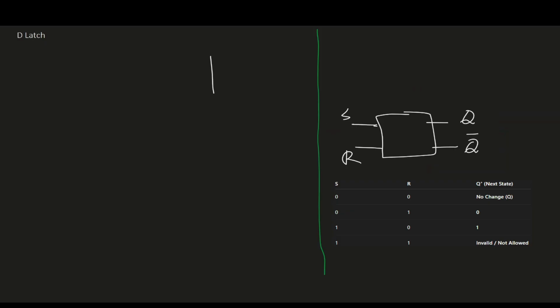So let's take this SR latch. We have the set input and the reset, and we have two outputs, Q state and Q bar or Q prime. Now to design the circuit for the D latch, we can add two AND gates, one for the set and one for the reset. We can use G, the gate, and tie it to both inputs of the two AND gates.